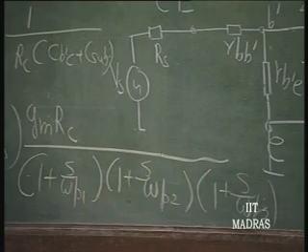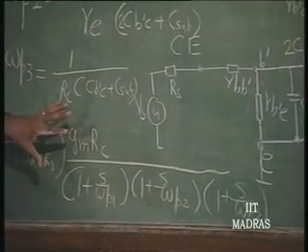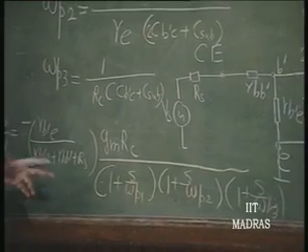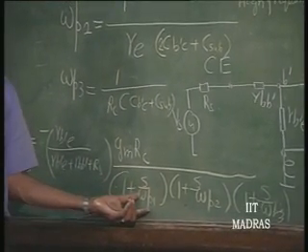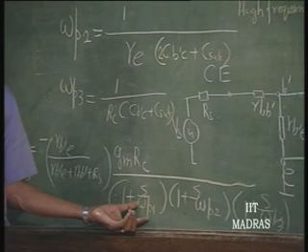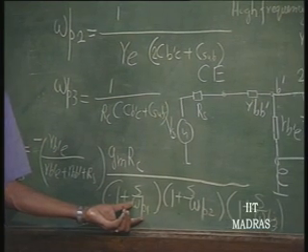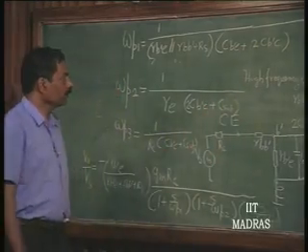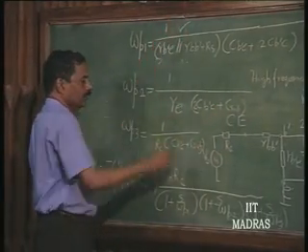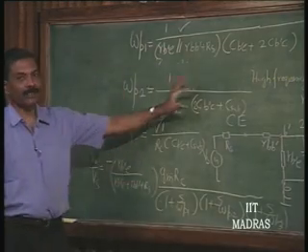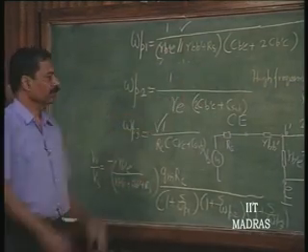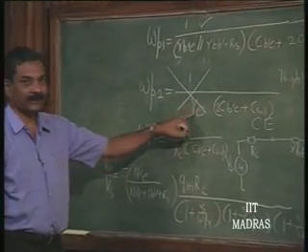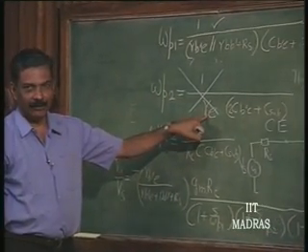Once again, you see that it is very nearly the same as the common emitter gain, except that now the time constants here have become lower than those of the common emitter. So, the bandwidth becomes higher. So, either this or this is normally very high. So, this does not come into the picture in most cases, because this is RE, right. So, almost nearly short circuit.